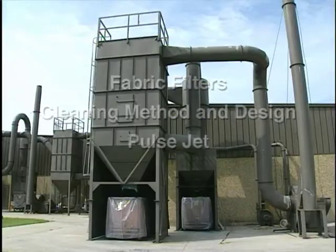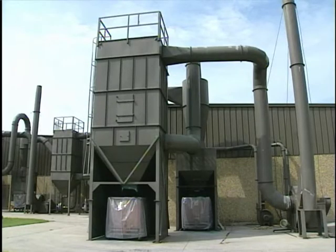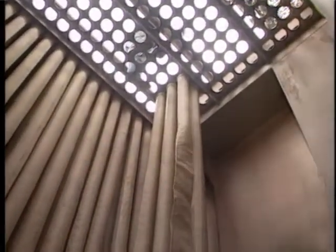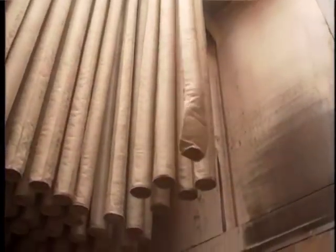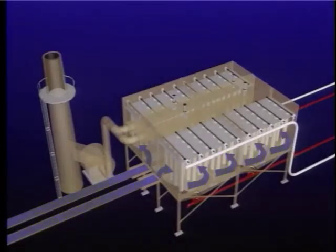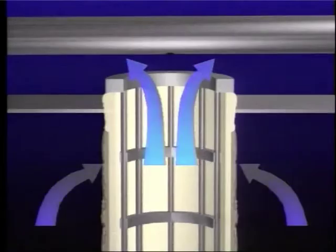Reverse pulse or pulse jet collectors clean the bags using short-duration pulses of compressed air. The collector has a tube sheet that is located near the top of the vertical casing, and the bags hang from the holes in the tube sheet. The contaminated gas stream enters through the side or hopper of the collector and flows into the bags and up through the tube sheet, leaving the dust cake on the outside of the bags.